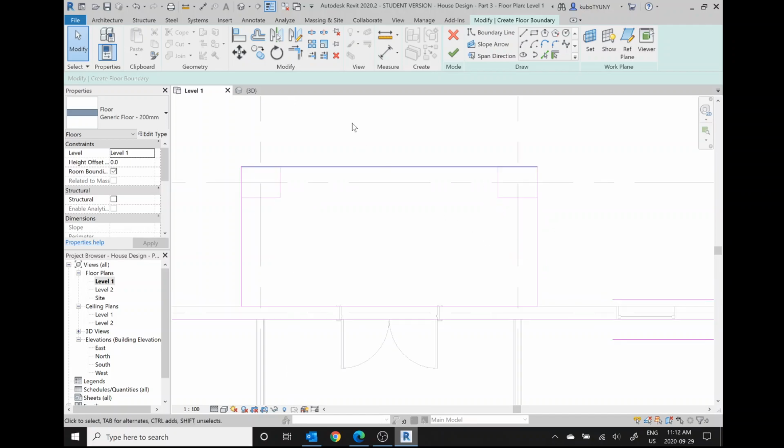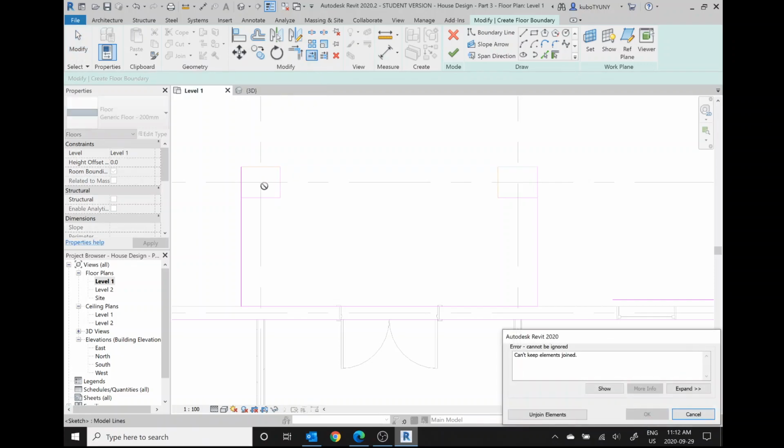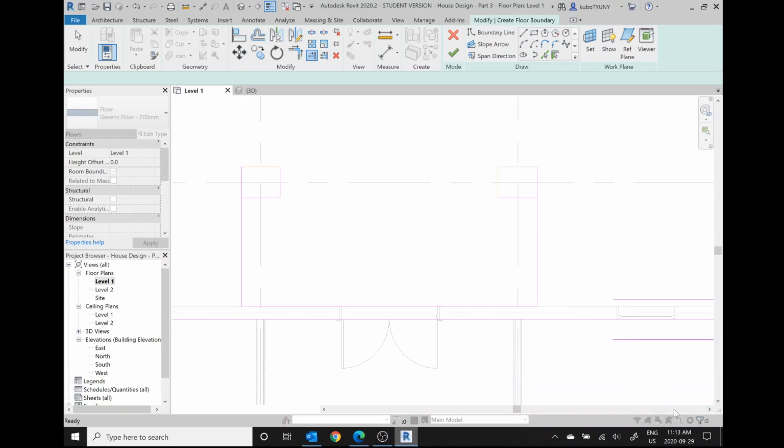slab. So what I'm going to try to do is, let's see if we can split, what is this, trim, extend, sure, let's see if that works. Oops, wrong side. Okay, so I guess the trim tool in trim extend multiple elements. Well, let's use the regular trim tool first. So here it looks like the rule is you click on the line that you want to use as a cutting line, and then you click on the side of the line you want to keep. Boom, there we go.